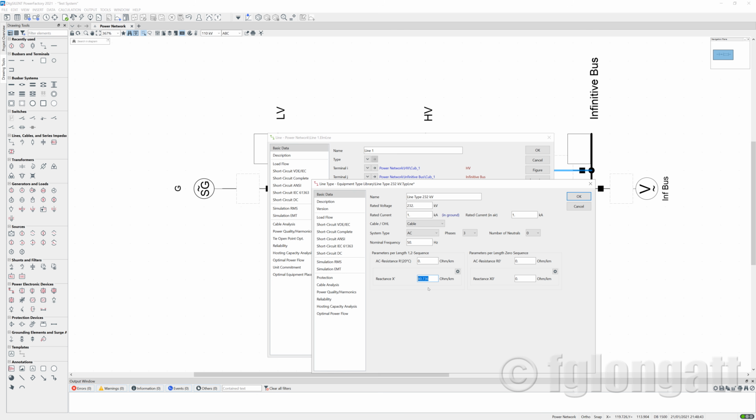What I am doing is including that number as the ohm per kilometer, and then I will say this is a transmission line of 1 kilometer. If we multiply by 1 kilometer, the length unit disappears, and we obtain the total 80.736 ohm, okay? Something that I will do here, to make clear that this is an overhead transmission line, okay? This is an overhead transmission line, and now I will say okay.